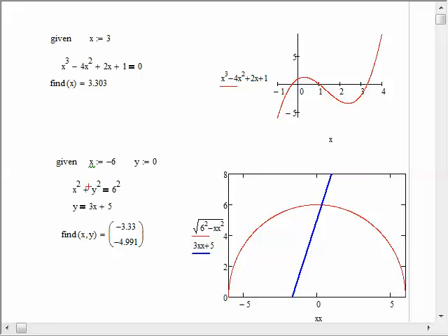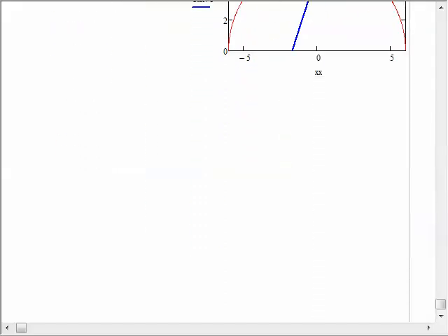Now how could you use this in your homework? First of all, you have a cubic equation that can be used to solve for the principal stresses in a full 3D Mohr circle problem. One way you could solve that cubic polynomial, many of you can do that in your calculator, but certainly a MathCad given find block would solve that one equation, one unknown problem. Then the other way you could put this to work is, and I'm going to go steal a picture out of the homework document and paste it.